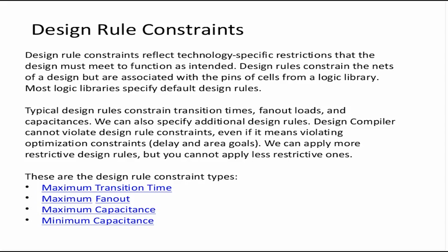So design rule constraints are technology specific restrictions that the design must meet to ensure functionality. If we go back to the libraries session and try to remember the nonlinear delay model, we saw that it is represented by a lookup table. For example, for a buffer or inverter, the delay from input to output and the transition at the output will depend on the input transition and the output load.